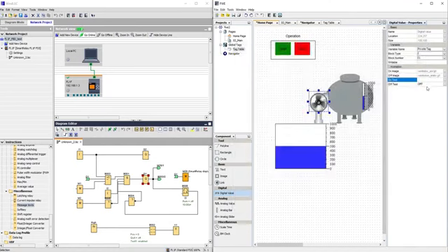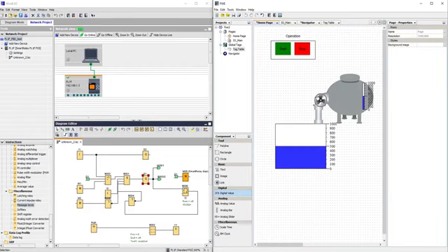Text, I don't want to display any on or off text. Delete for this, no. And tag, I'm going to use private tag Q1, that is output number Q1. I'll reduce this size, right? So we'll understand that the pump is pumping from one tank to another.